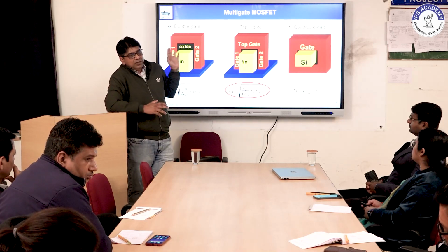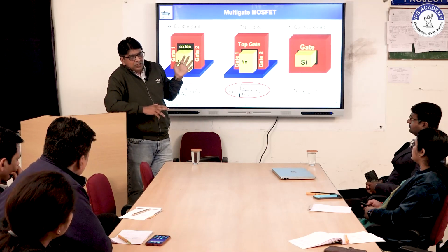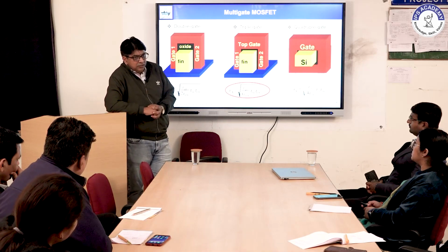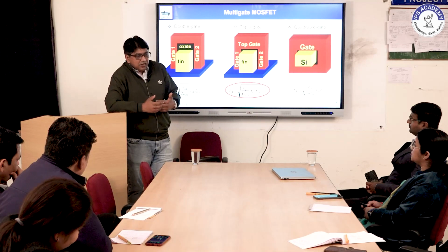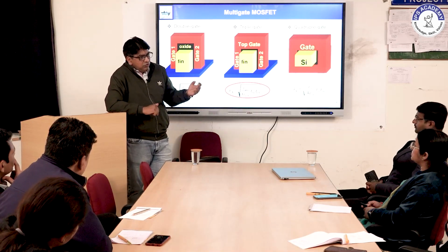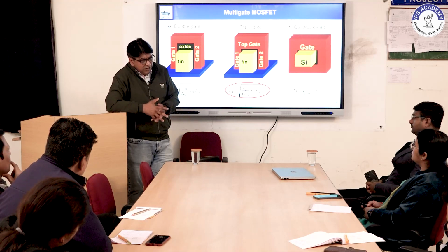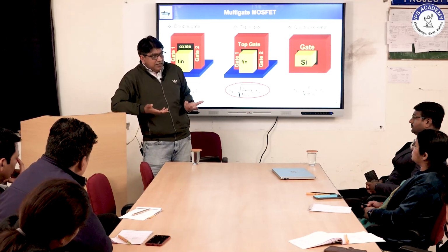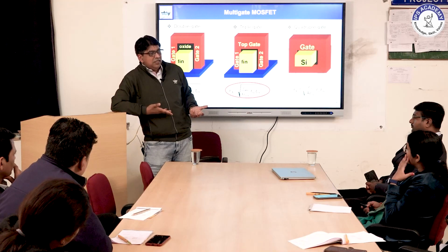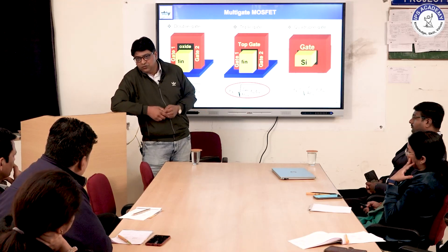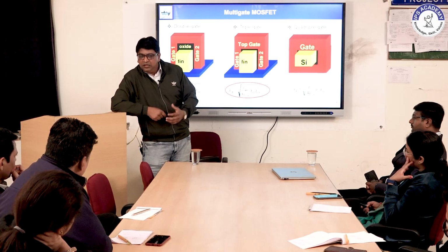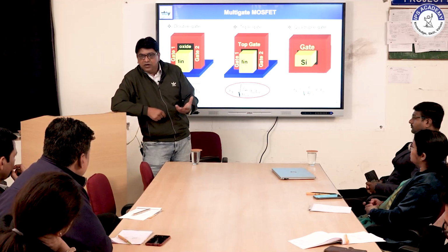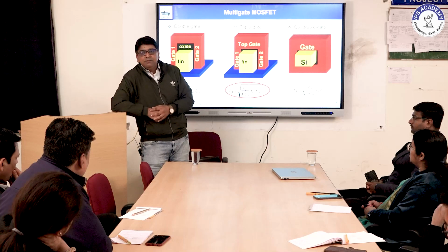So what is happening? Double gate solved the problem at 22 nanometer, then we came to 14 nanometer. Again leakage started, so we used the help of tri-gate, introducing another gate, and scaling continued. Then we come to 3 nanometer, again 5 nanometer, and again we face the problem of leakage, because we have to maintain the on by off ratio. If the on current is good but the off current is the same amount, that is not a useful device. If the device is idle in a circuit, it will drain the power from the power supply, which means our system will not retain battery backup for a long time. This is the big challenge.